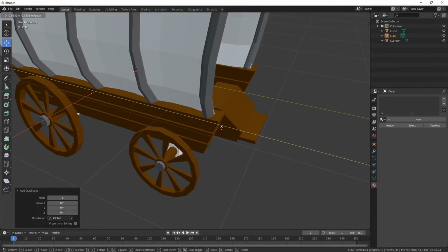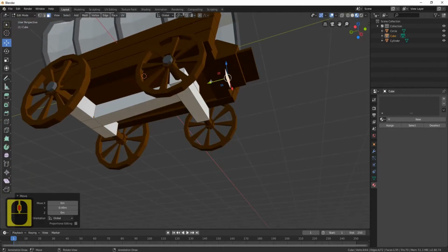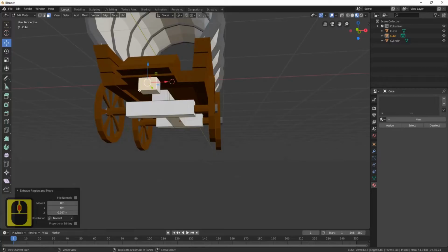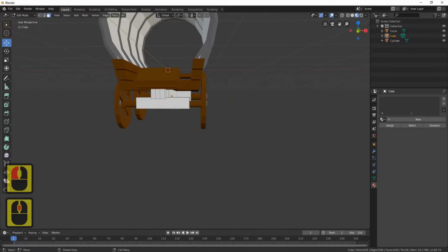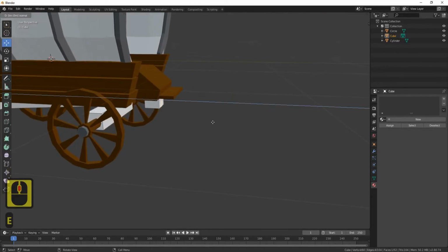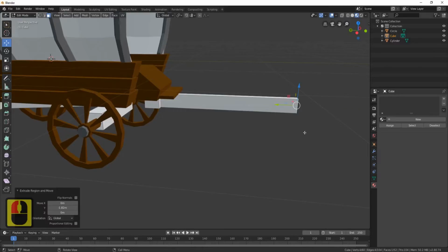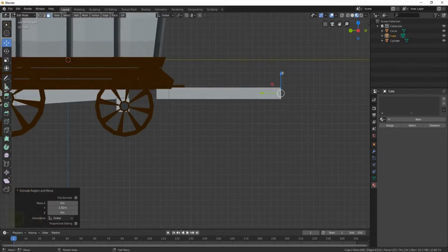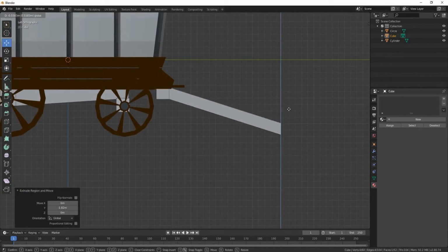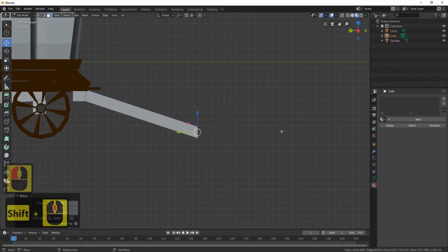Okay, we'll use this face now, so click on this face, Shift D, and bring it to the front, to just under here, extrude it out, press Ctrl R, 2, left click, right click, go into face select, let's grab this face, E, Y, drag it out, press Ctrl 3, and now let's bring it down to the same level as the wheels,